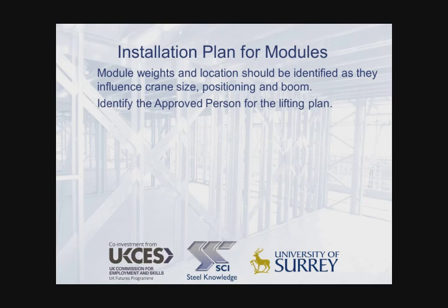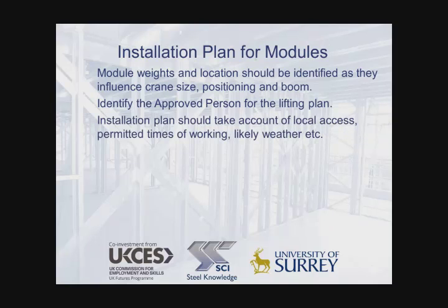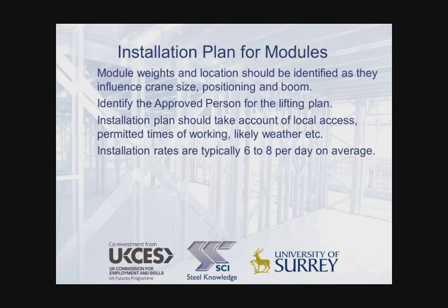It's also necessary to identify the approved person who's responsible for preparing and administering the lifting plan. And this should take account of local access, permitted times of working and weather conditions, etc. A typical installation rate is 6 to 8 modules per day on average, taking account of these factors.